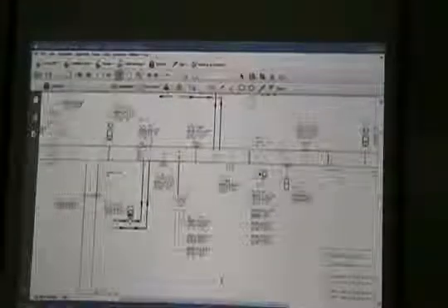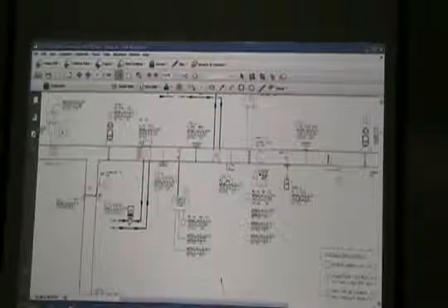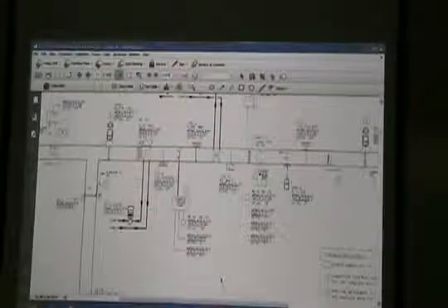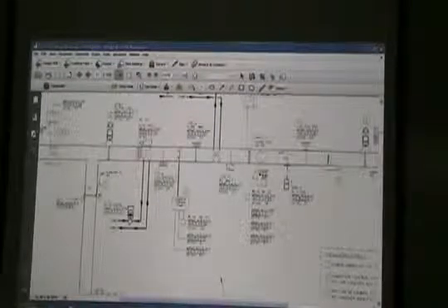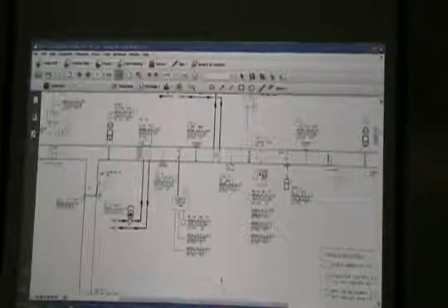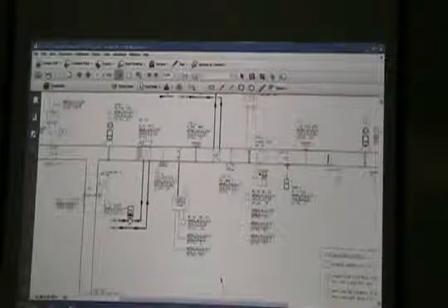So to truly do what the engineer is asking us to do, this temperature transmitter right here should be truly in the mixed air before everything else is happening, so we can truly know what the mixed air temperature is. We got return air coming back at 70, 72 degrees. You got outside air in the wintertime that could be coming in at 10 degrees, mixing with that 70 degrees.